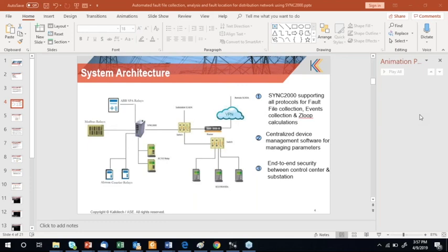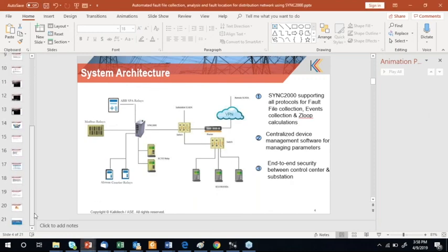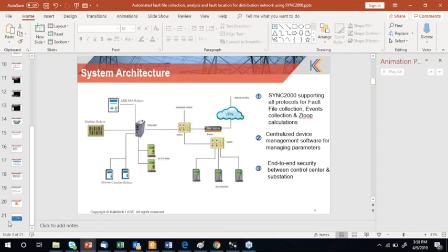For the project, the requirement is to collect the configuration from the IEDs, then compare it with the master configuration file that is available, and whenever a change is detected from the available configuration file, we need to throw an alarm. So that we are now working out. We have been successful in implementing it for relays, and we are working on other relays also. So automatic configuration file retrieval and making it automatically available to the databases of PSCS.